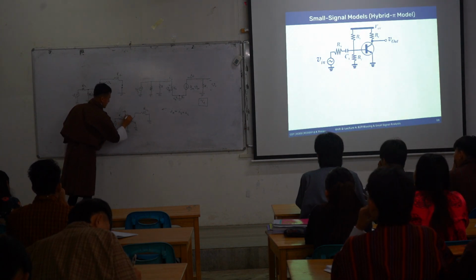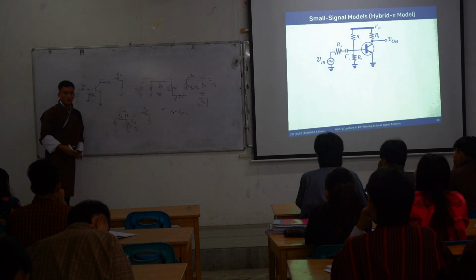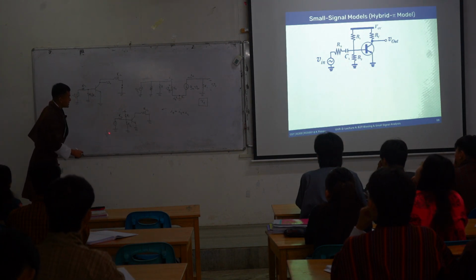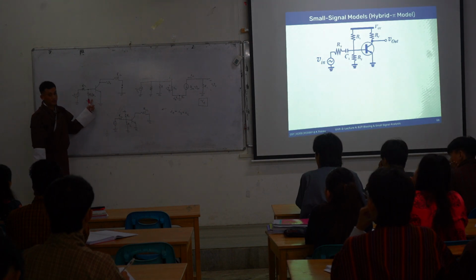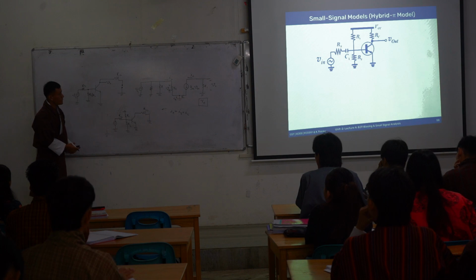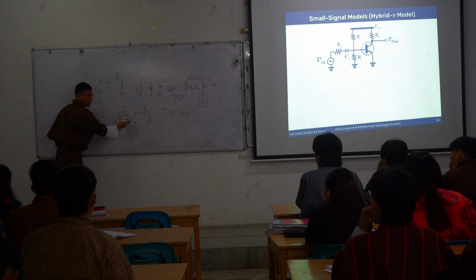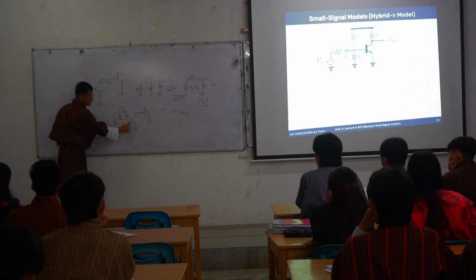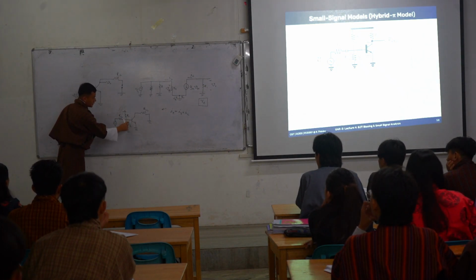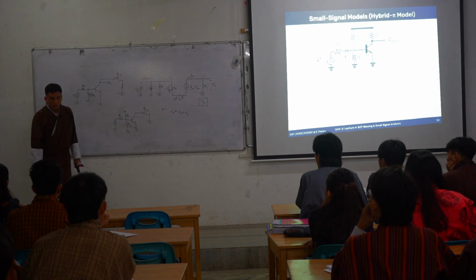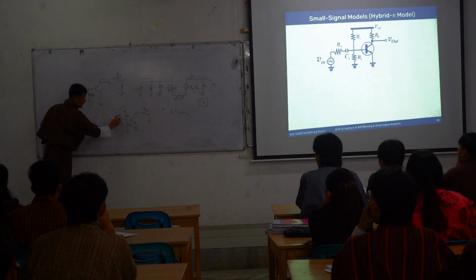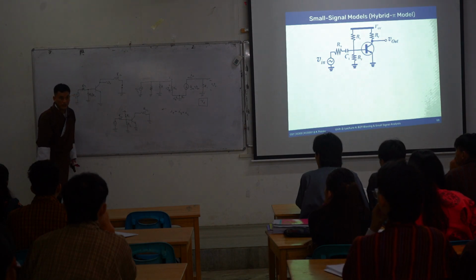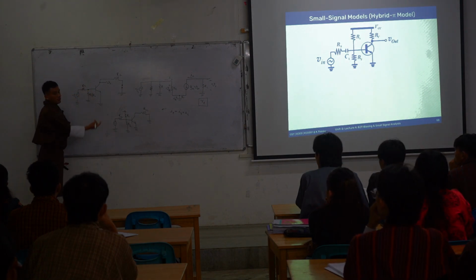This will be the simplified version of this particular circuit in AC. Now, if you simplify this one, you'll end up getting this particular circuit. If you see here, this is your input side. Looking into the input side, R1, R2, RS, they are all parallel to each other. So I can represent R1 parallel to R2, then also RS parallel with R1 and R2.